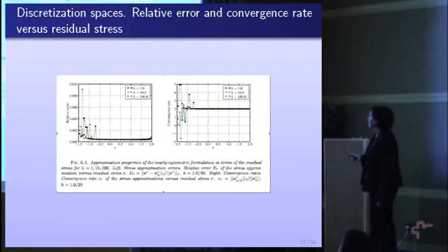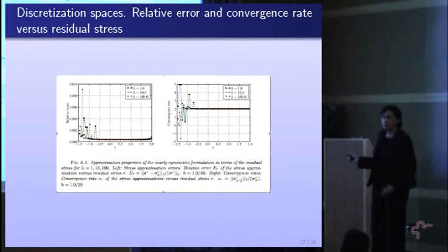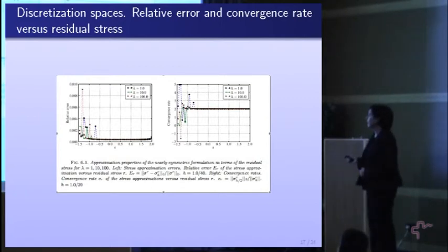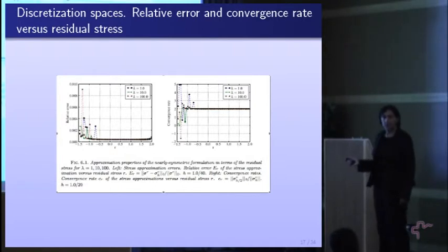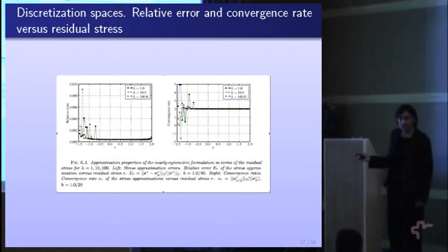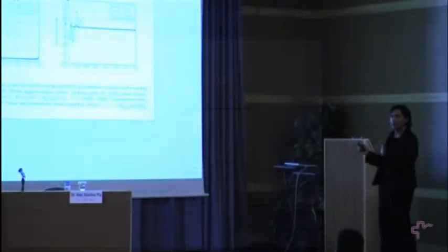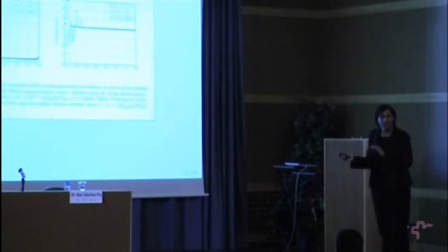Okay, what we have here is the residual stress. If we have negative residual stresses, like pressures, then one has to be very careful, because the convergence gets very shaky, and also the stability of the method gets very shaky. In this case, if the material has to sustain this kind of residual stress, then a better numerical method has to be in place. So this is just to point out some of the issues that one has to look at when you do